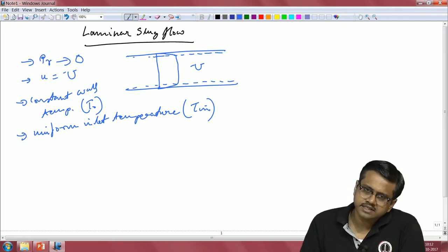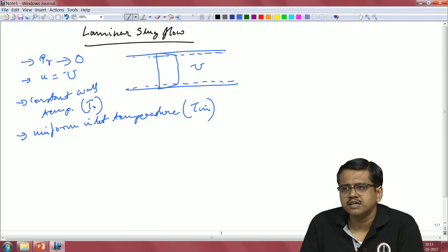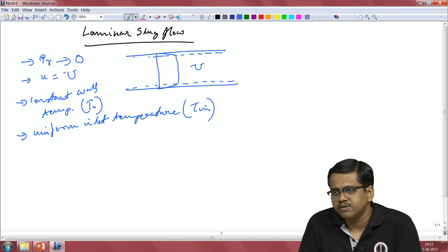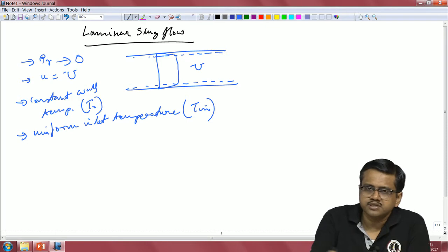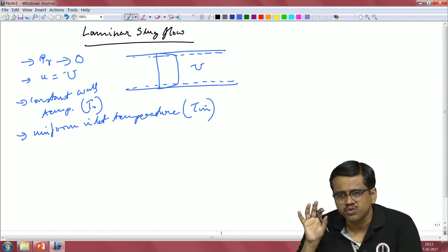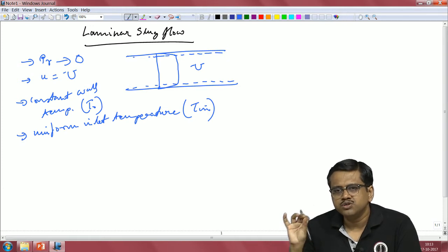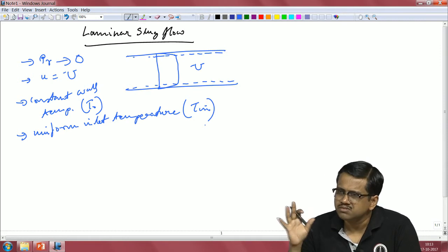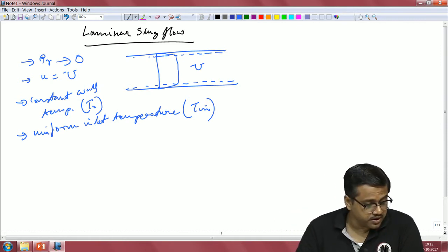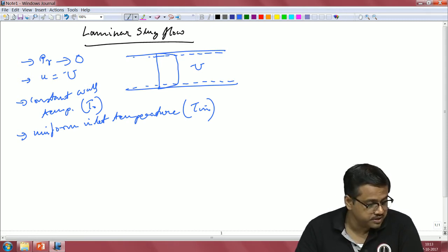So, the only thing is that instead of a fully developed velocity profile, which is a function of r, here we have a constant value of the velocity, which is u, mainly because of a situation like this. So, this happens a lot in the food industry, because if you are trying to push say solid food or semi liquid kind of food through the pipes, there usually the boundary layers are very thin. As a result of that, your velocity is kind of uniform across the cross section. That means the r dependence is not there anymore. That is what I am trying to say.